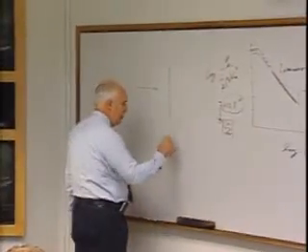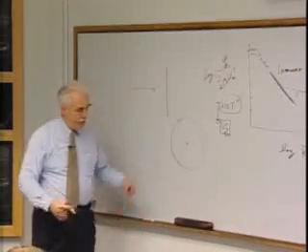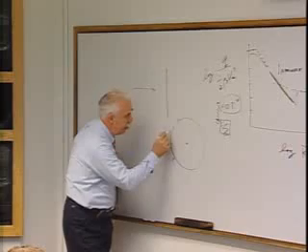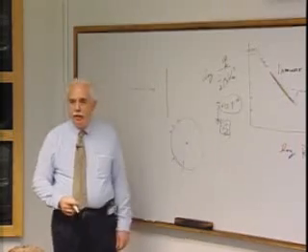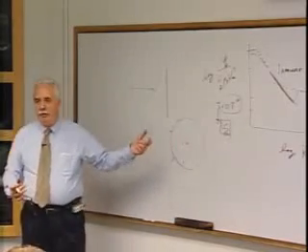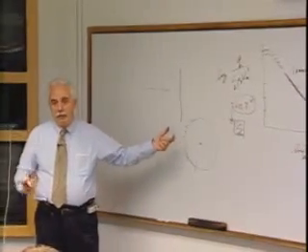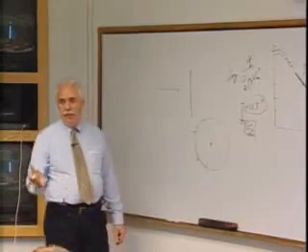Okay, so let's go to a sphere. Now, the center of pressure, no matter where the pressure is on the vehicle, no matter what the pressure is, it goes right to the center, okay? And that's probably also about the center of gravity if I flew a sphere. Certainly if it was solid, but if I build a spherical spacecraft, it would be neutrally stable.